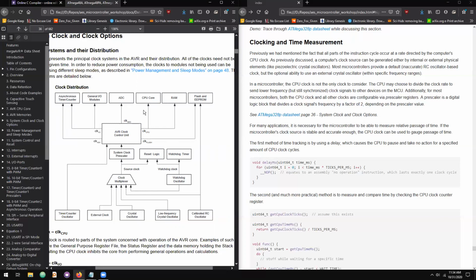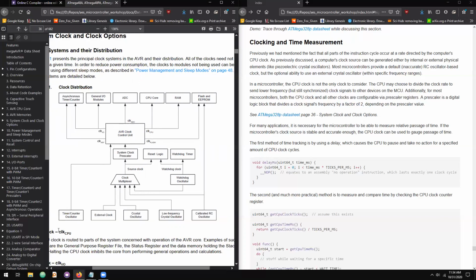Like a generic computer, that clock signal produces a CPU clock signal that allows the instruction cycle to execute. But also, the microcontroller will break out that clock signal to provide dedicated clocks for each of the features and functions that it offers.